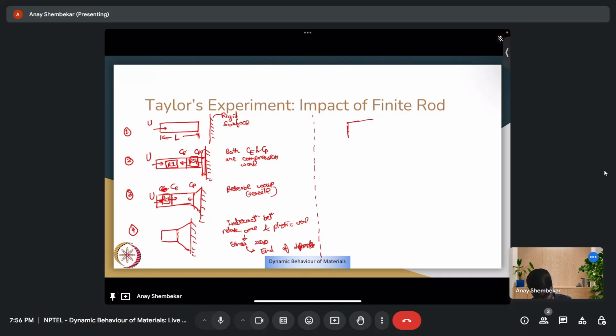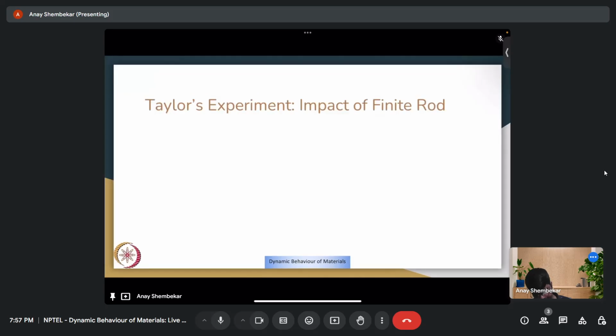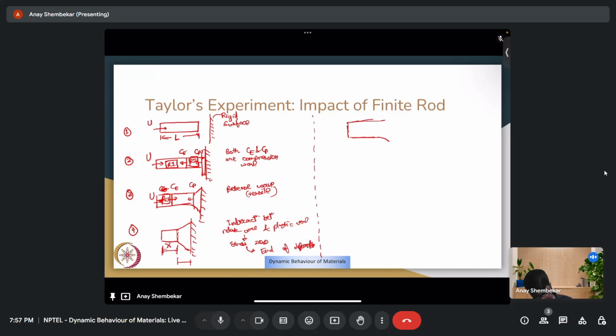Suppose I now draw this. I'll write this is capital X, L1. Suppose I now draw a schematic. This is velocity u, initial area A naught. This is the plastic wave front, velocity v. This is the final area A. Somewhere in between, you have the elastic wave front with velocity c.